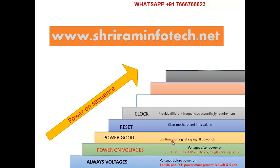First try to replace the crystal. If still not solved, then you have to replace the PCH. So that is like that. After that, the next chip is called the BIOS. All the chips are available in the market. The next chip is called the BIOS.